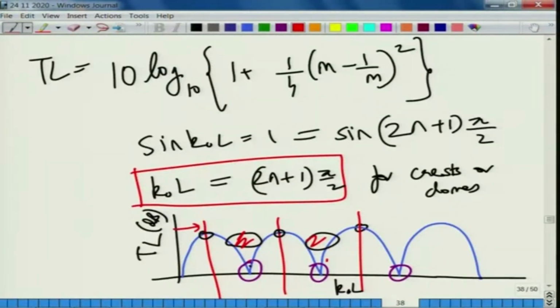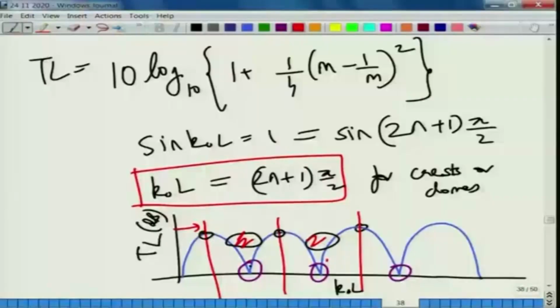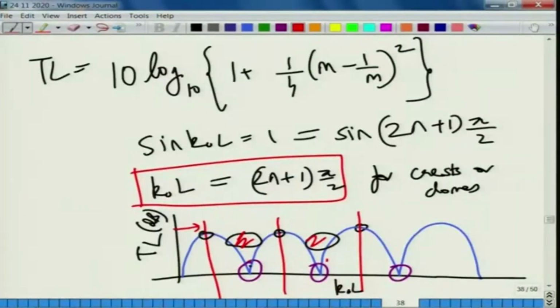So, there is some kind of a bottlenecking or limitation imposed by the trough, and this is especially important because automobiles are basically a variable speed drive, because the speed changes and the RPM of the engine changes, and automobile engine exhaust noise is dominated by the first firing frequency and its multiples. So, if the speed changes, the RPM of the engine changes and the firing frequency obviously changes. So, the frequency spectrum keeps on changing based on different RPM, and for such a variable speed drive the noise spectrum continuously changes.